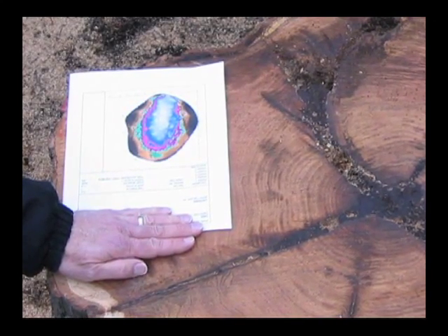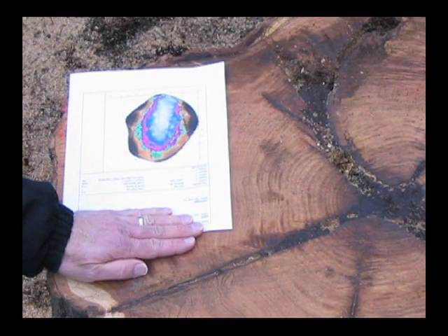Acoustic displays of cracks, for example, are usually overstated in the tomogram. Areas of low velocity could be a result of decay, hollow, snake crack, or ring crack.